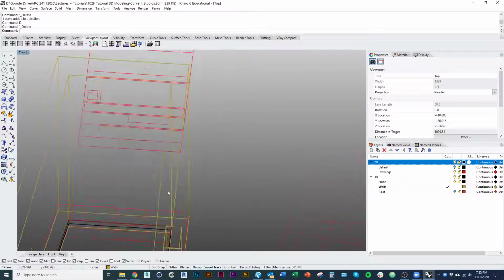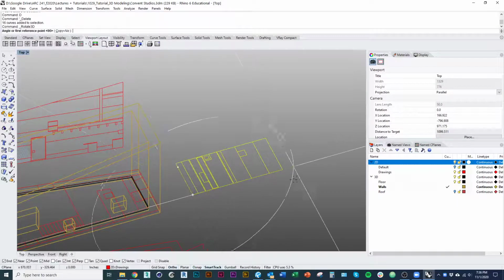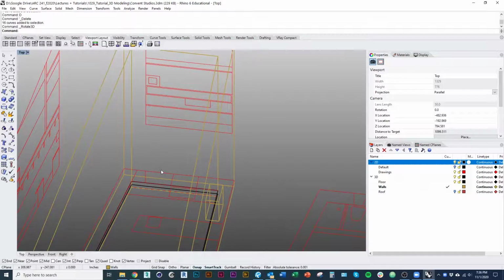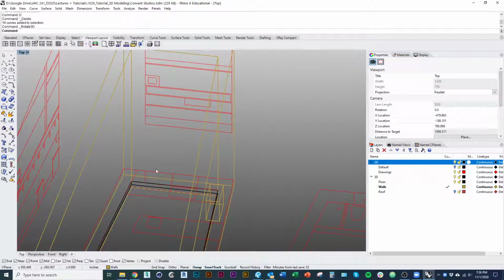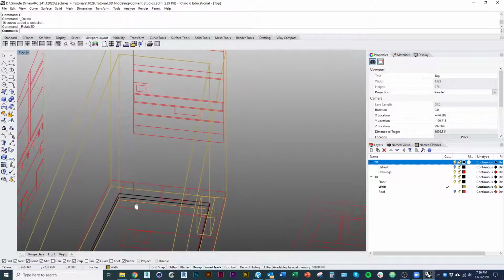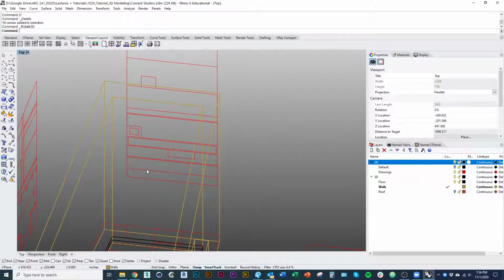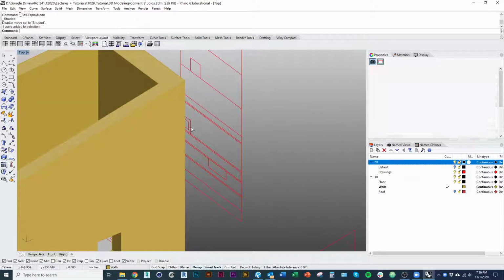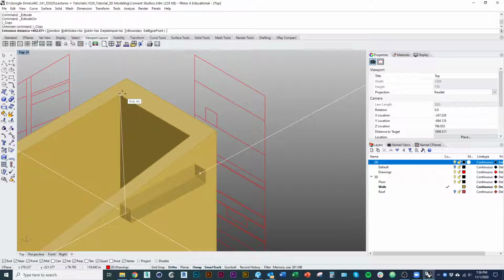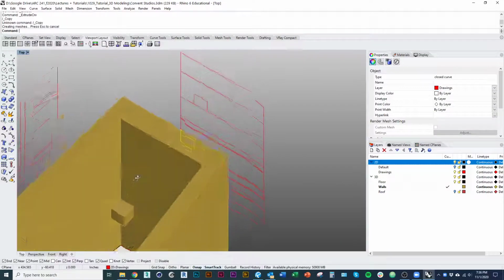So I'm going to do the same thing with this. I'm going to rotate this drawing vertical so I can use it as a reference point. Then I need to figure out how I'm going to make a volume that's this shape in order to trim away, not just a straight planar extrusion. I can do that a couple different ways. First, I'm going to start by taking this outline and extrude it through the inside, beyond where it intersects with my wall.